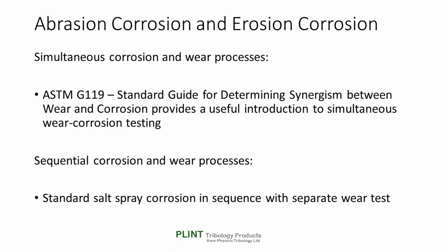However, in some applications, corrosion and mechanical wear processes are not concurrent. For example, an out-of-service system may be subjected to corrosion, but with nothing moving. It may subsequently be moved away from the primary source of corrosion and into operation, subjecting components to mechanical wear. In this case, the wear is not taking place at the same time as the corrosion, but is taking place on parts previously exposed to a corrosive atmosphere. Think perhaps of putting a rusty piece of machinery back into service.